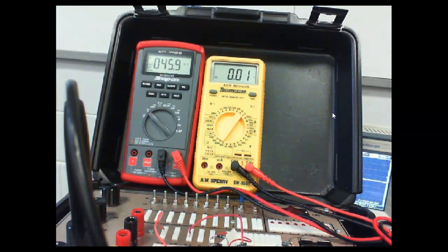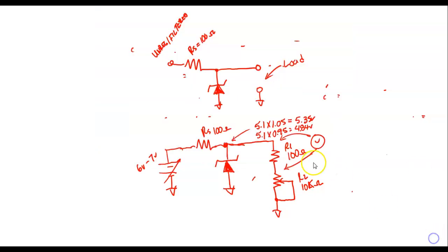So I've got a 100 ohm resistor right here. We're going to use this as our shunt. What a shunt is basically something you're going to measure from. Okay. So what we're trying to do is get 2.5 milliamps and 7 milliamps across a 100 ohm resistor.